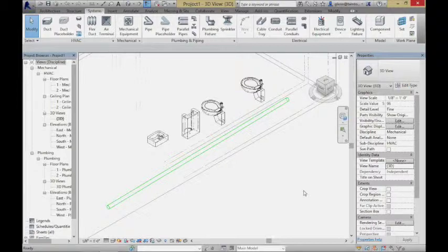There's a lot of variables in there. So what I'm going to advocate you do, as opposed to just always using auto routing, is go through and, if you know that there should be a lateral that's going to run through that wall, give it some help. Don't lay out every last connection, but give it the main idea of where you want the big pipe runs to be. Get that part laid out.